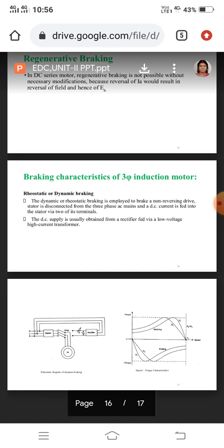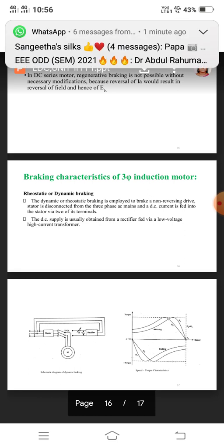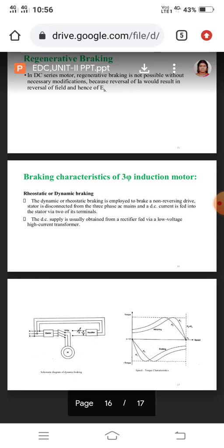specifications for which it is possible to use the motor for continuous rated operation. It is designed to be used in a single direction. The number of rated revolutions depends on the load imposed on it. So this characteristic of the induction motor is very reliable. The characteristics and voltage can be represented by the torque characteristics also, the torque characteristics about the applied voltage. The torque of the induction motor changes in proportion to the square of the voltage.